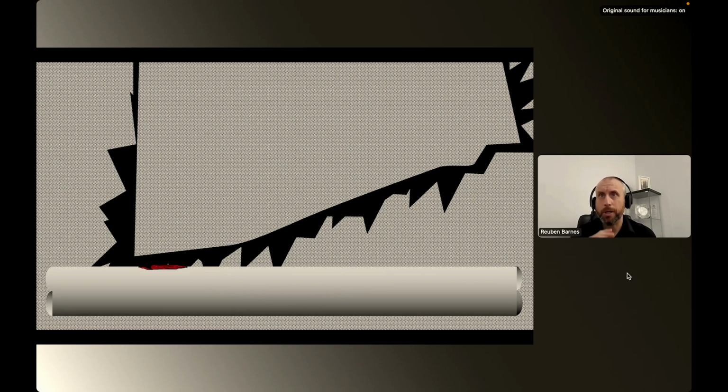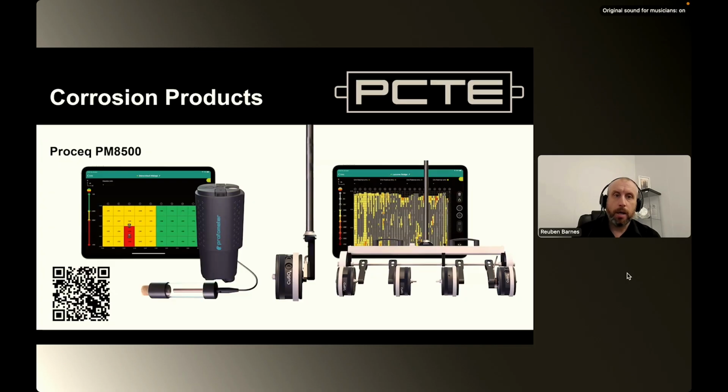Once the spalling has occurred, the steel is exposed to the environment, and the whole thing becomes quite chaotic and quick, and we can move to total section loss of the reinforcing quite quickly. So that's basically setting the stage for the tests that we want to carry out.